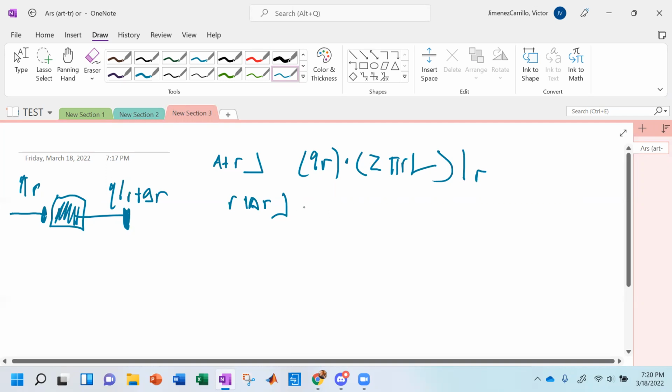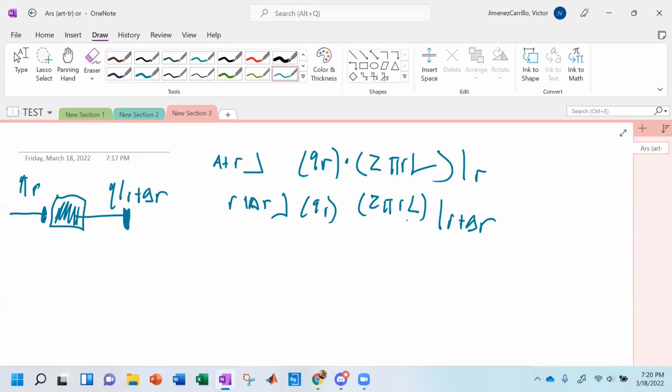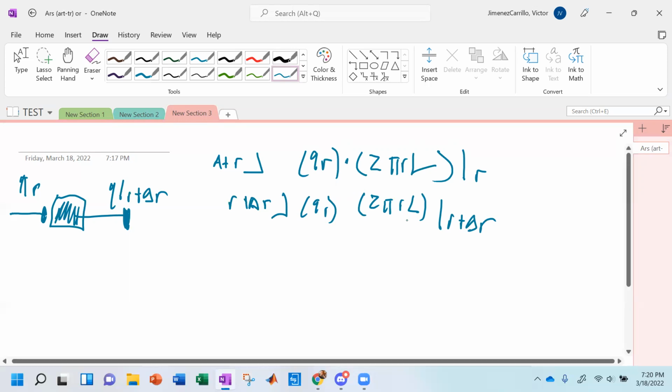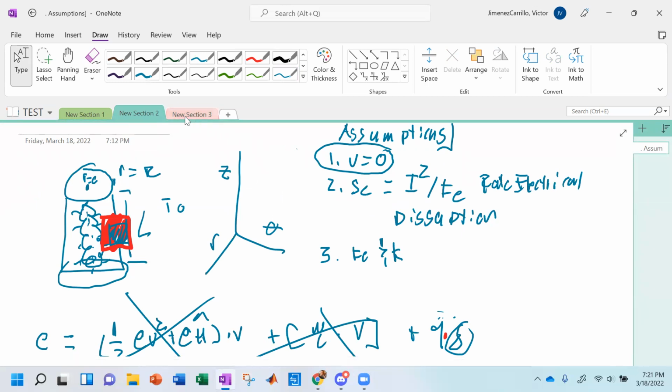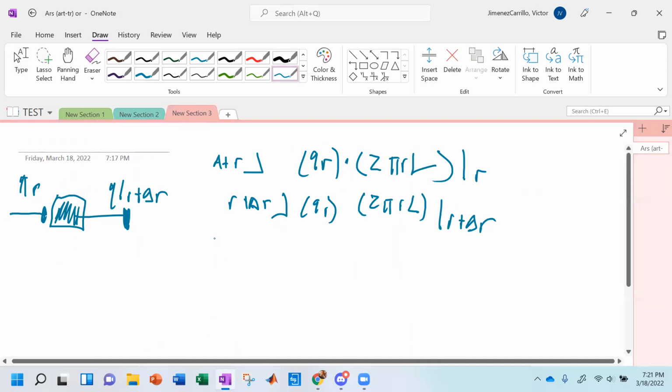Okay. How about at R plus delta R? Do you think the area is going to change? Unanimously, beautiful, because it's the same surface. Now, is QR going to change? Kinda. All that changes is that we're at R plus delta R. Now, ladies and gentlemen, what's the external force on my system? Is there any? There's no flow, so is there? Nah. Good. But we did say something else. We need to talk about the rate of heat production. And how did we decide to model that rate of heat production? That S_E right here. We do have to take that into account. So normally in your shell balance, you'll write thermal energy.